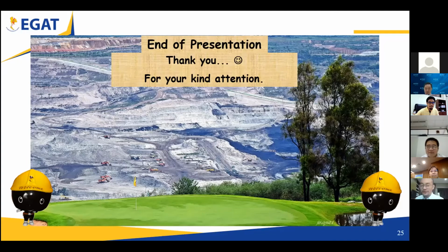Have you tried refining the mesh? How can you be so sure that your result is accurate, because you have 37,000 grids for 44 square kilometers? You mean your grid is very large, it's quite a coarse grid, or is it that you reached any limitations? I refine the grid in the pumping well only. Only in the pumping well. Oh, okay. All right.